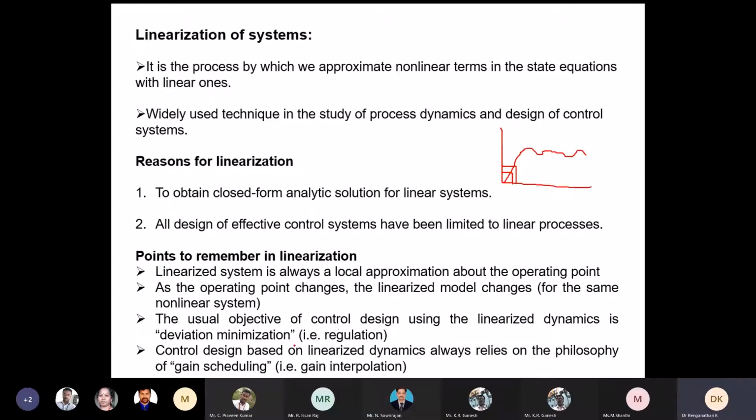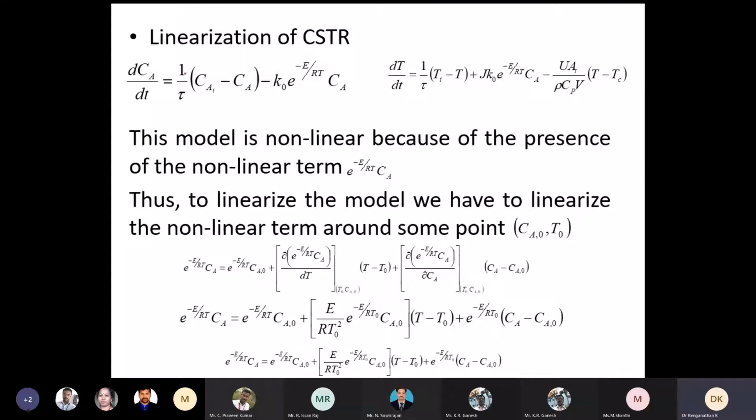Let's move to the next slide. So obviously, for the linearization of the above equations, we are just going to use the normal Taylor series approximation, or we can go for any kind of approximation technique. Because of this, in this expression, the nonlinear term is going to be linearized. So we go for the Taylor series approximation to linearize this system, to remove this exponential component out of the expressions shown here.